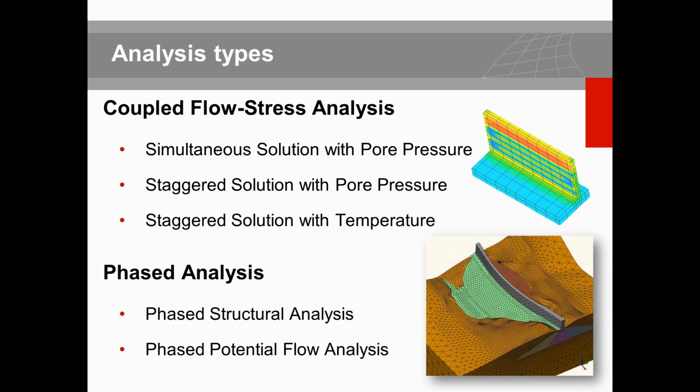For phase analysis, we consider the full process of construction or erection of the structure, or decommissioning and demolishing of the structure. Moreover, you can combine this concept of phase analysis with potential flow. For instance, you want to see the variation of the nonlinear effect on the structure in time. So after 10 years, 20 years, changing the season, how is the model behaving, how is the crest, for instance, in this dam changing.